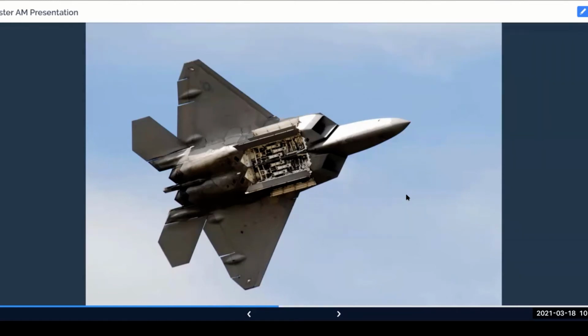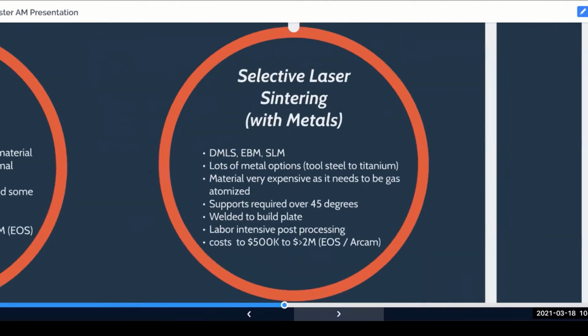Well, again, this is the same time that this polymer 3D printing SLS technology was being developed. They brought in UT Austin, Carl Deckard, and 3D Systems, which had just bought them. They printed an air intake that did this thing in polymer, mounted it to the test engine, and it worked flawlessly. Now every F-22 Raptor that's flying today is flying with two 3D printed air intake manifolds. Talk about something that's in really intense conditions. This is at the start of a turbine engine sucking in air at incredible rates of speed, and that was the manufacturing solution.